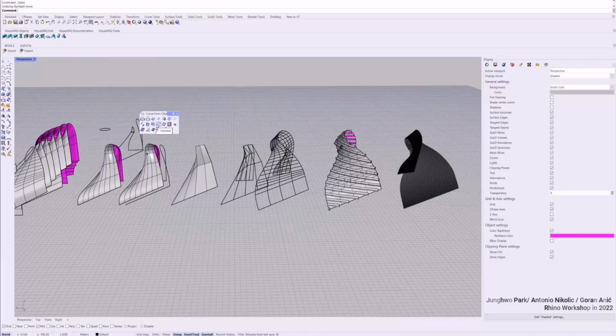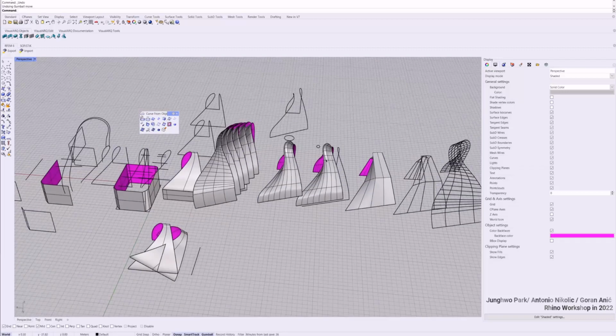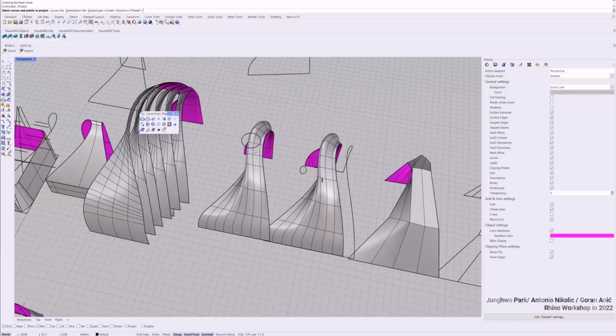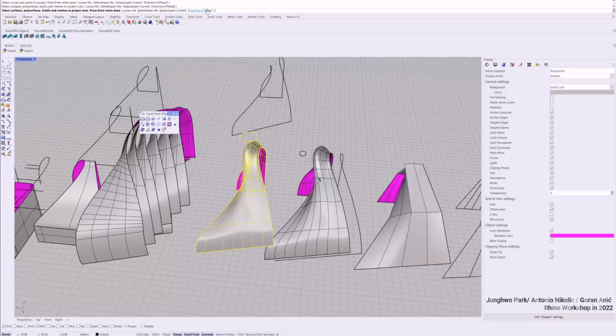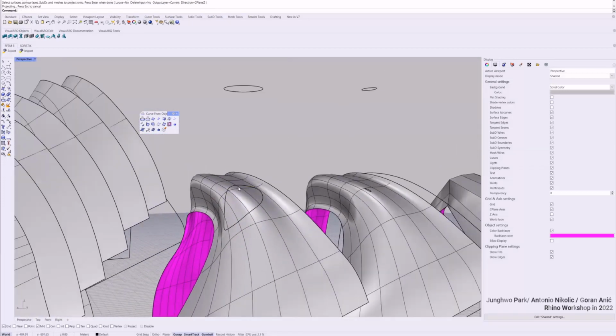We had wireframe, extract wireframe, intersect. All the others are not very interesting, I guess. You can also draw a section line, which we did. Silhouette you can get, nothing particularly interesting. But there's an interesting point between project and pull. Projection is basically you can project a particular curve to the construction plane, in this case the C plane Z axis, so you get this projection.